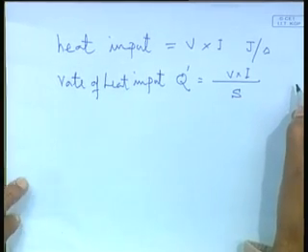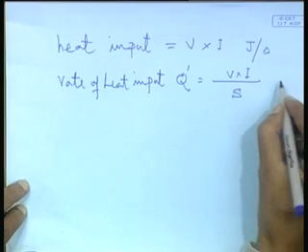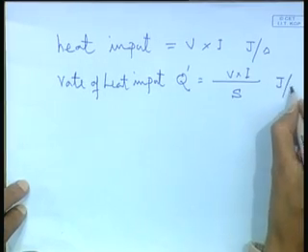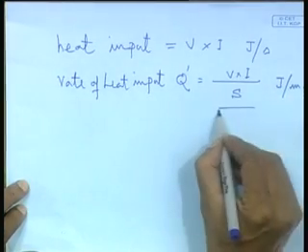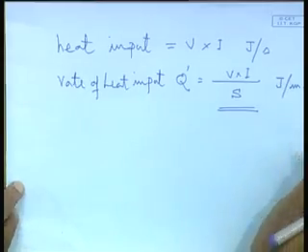If the speed is in, say, millimeter per second, then it becomes joule per millimeter. So, this is what is important, that means what is the amount of heat going in per unit length, instead of per unit time. Here we are bothered about per unit length, that means the total quantum of heat going into the structure. So, that is what is important.